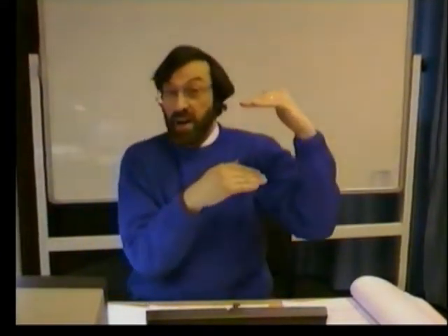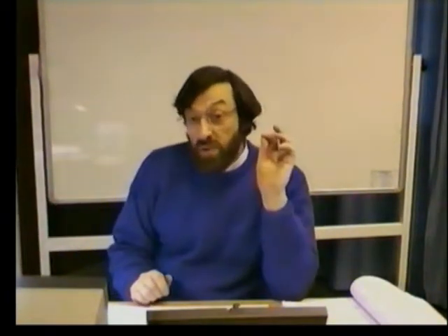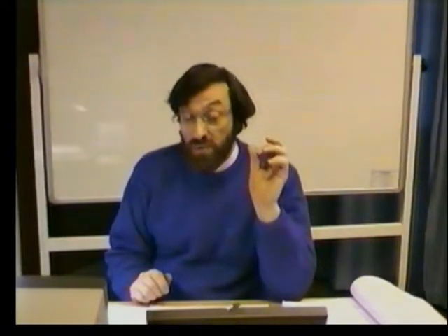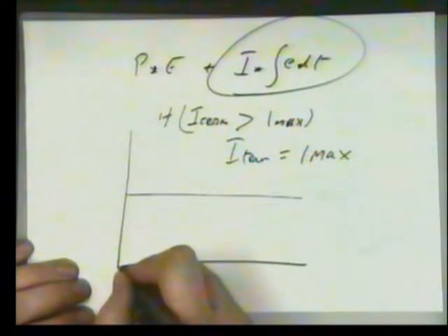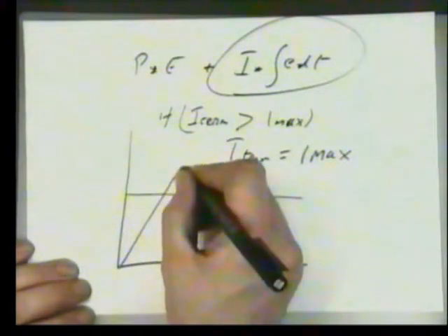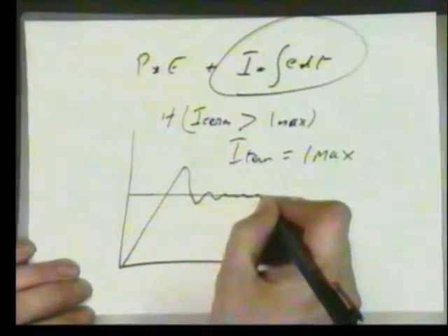The integral clamp simply puts a maximum value on the I term. Very simple, very easy. And all that happens is that if you look at the response of an integral clamp system, whereas it was running away before, the nice thing about it is that you still get the very, very high speed response, but suddenly it drops back and comes into control.